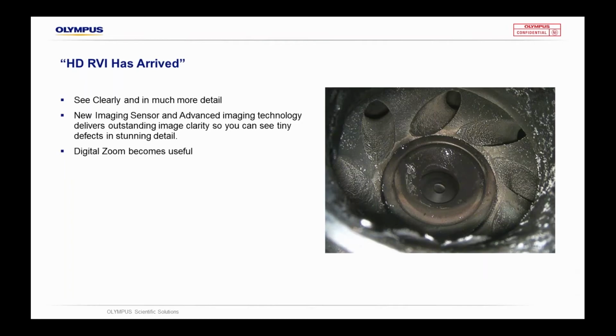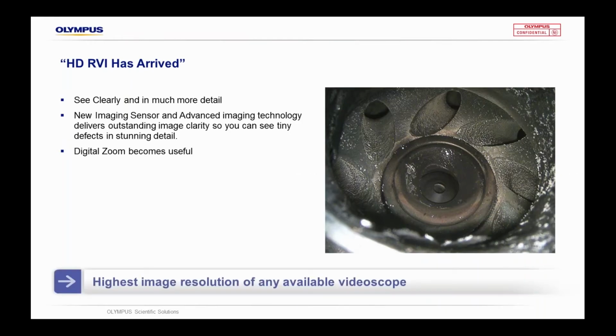Moving forward from that, we've got a new high definition sensor which is used in the tip of the scope. When you increase the pixels, as an example, when it comes to high definition, you have more pixels. More pixels gives you potentially more resolution. The problem you have there is that by introducing more pixels across the same surface area, these pixels then become slightly smaller, and therefore their light capturing ability is not as good, even though the resolution will become higher.